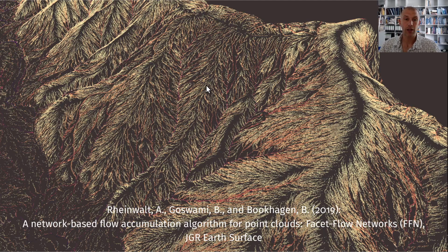Last but not least, I wanted to point out that you can also use point clouds to perform flow routing. This is specifically of interest to geomorphology or hydrology. What we have mostly been doing is generating a DEM, a 1 meter DEM for example, and then flow routing the surface water over this area.